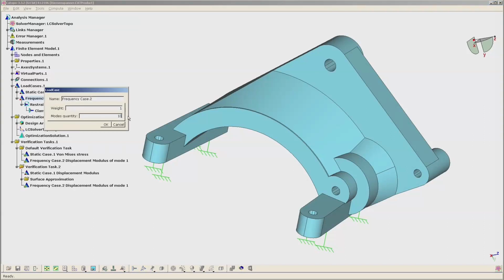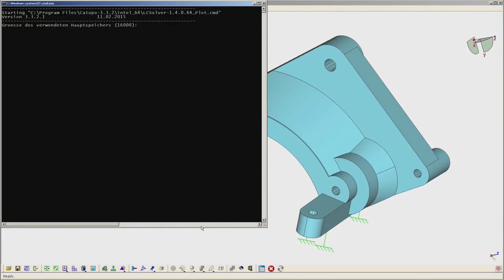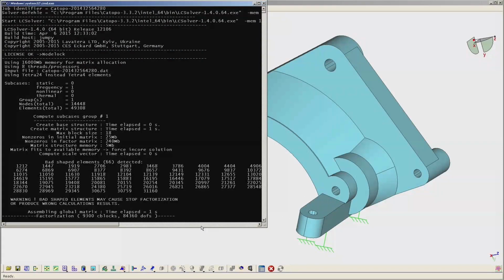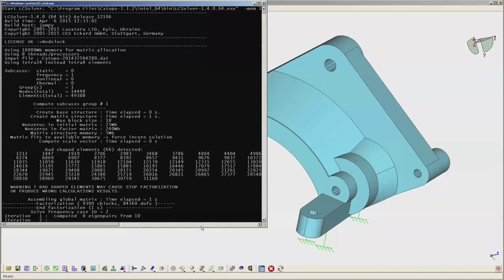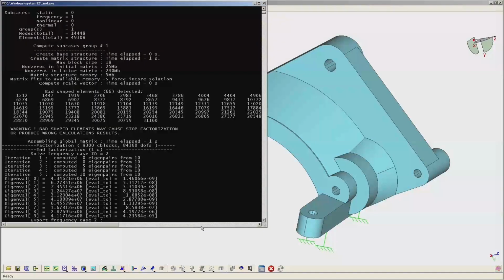We just create a new load case, and now we use this new load case on our new shape, and we will do an eigenvalue analysis. Also, we will do it in live time here. It's approximately between, let's say, 40 and 50 seconds, I expect. And after that, we can analyze the eigenvalues.